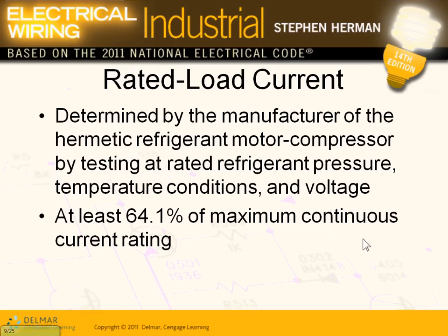Rated load amps, the way they do the rated load amps, the only thing I want you guys to highlight is this one. They take the largest amount of current that the equipment can handle before it starts smoking, as it compresses the refrigerant and circulates and does all this refrigerant cycle. And then they take 64% of it, and that's what they call the rated load amps. 64% of the largest current before smoke starts coming out of it, or it blows up or whatever, and they call this the rated load amps. You don't have to know that, other than for the test.